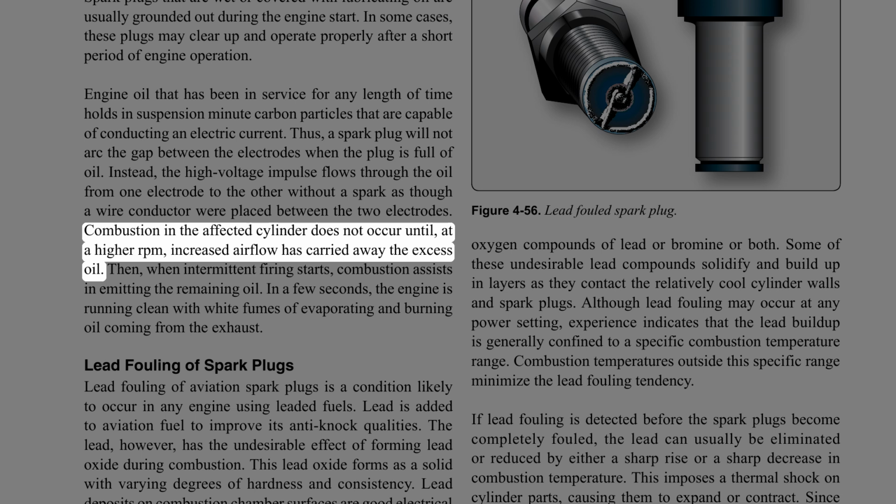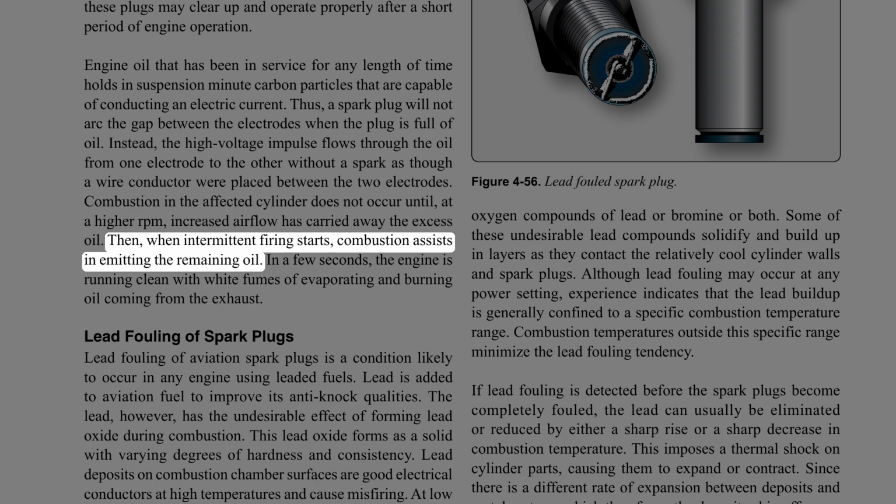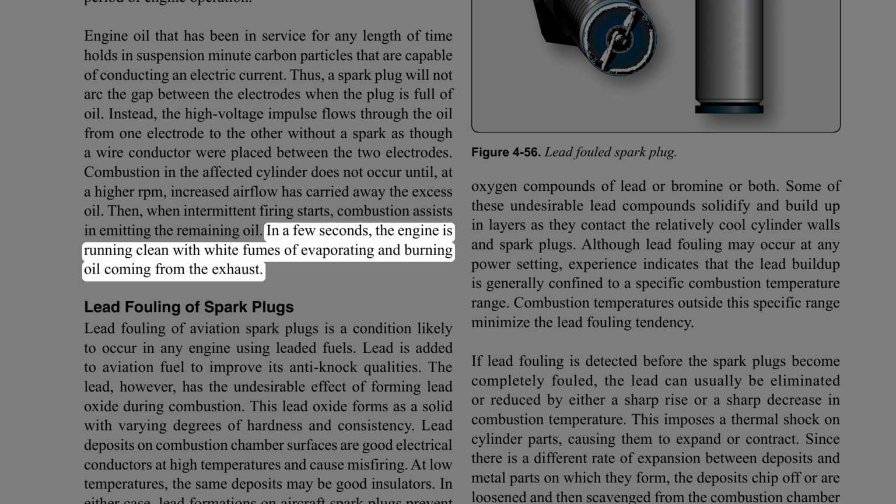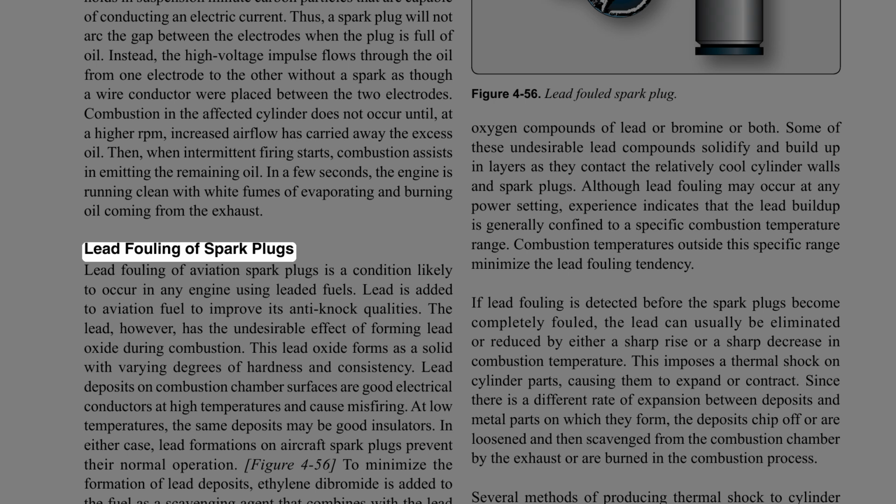Combustion in the affected cylinder does not occur until, at a higher RPM, increased airflow has carried away the excess oil. Then, when intermittent firing starts, combustion assists in emitting the remaining oil. In a few seconds, the engine is running clean with white fumes of evaporating and burning oil coming from the exhaust. Lead fouling of spark plugs.